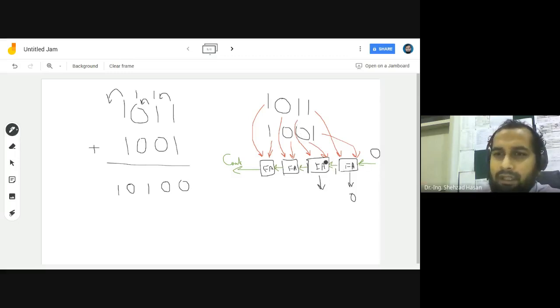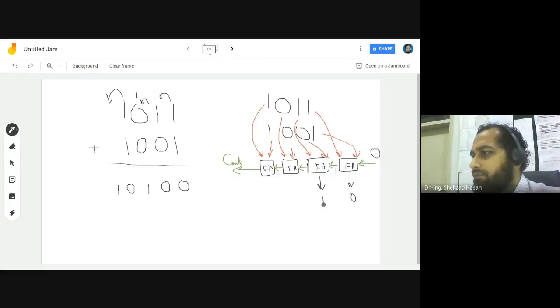So it's going to add just 1 and 0, and here the carry input would be 0 initially. It's going to give a 1 over here, right? Similarly, 0 plus 0 and 0 coming from this side is going to give a 0 over here. And 1 plus 1 is going to give a 1 0 over here. Okay, so this is our first step.